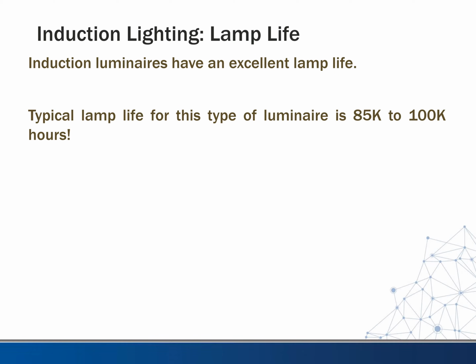Probably the spot where they win out against all other lamps is in lamp life. These lamps do have an incredibly long lamp life, probably due to the use of the electromagnetic field to excite the mercury. There's no anode or cathode, so that probably gets rid of some losses there. And so these have been rated anywhere from 85,000 to 100,000 hours for use.